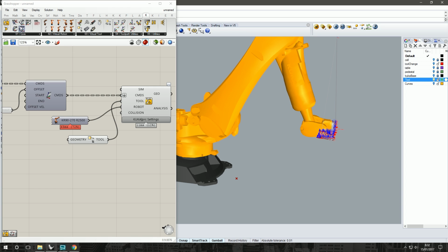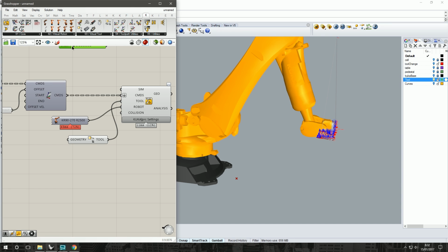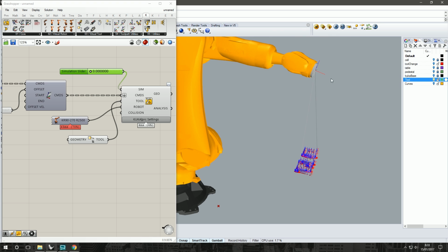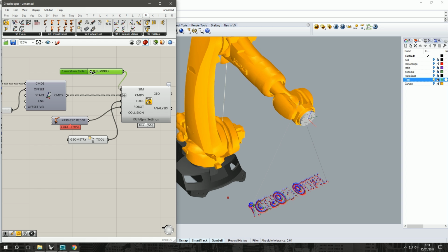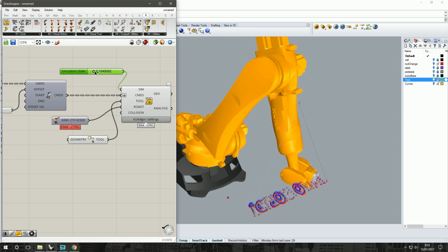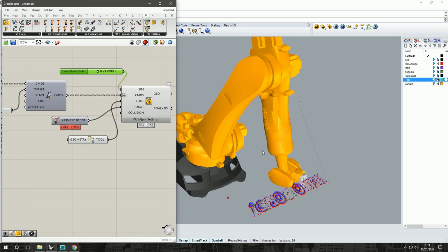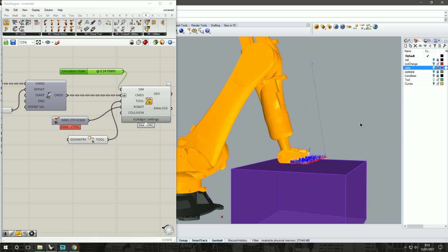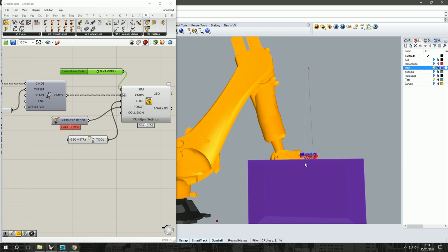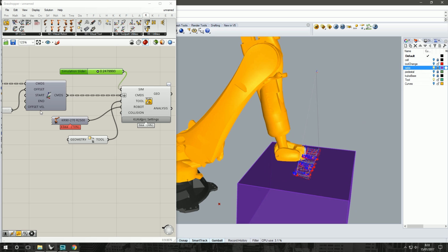Now you'll see if we put a number slider 0.0, give it plenty of floating integers to 1, we can then control the simulation. So there's our start point, 0. We drag this through, that simulates our robot. Now you can see straight away something's not right. If we show the table, the KUKA is colliding with the table, and we know that the pen's going to be coming off.